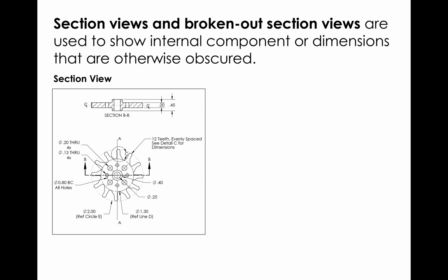Okay, so this is the trigger. This is my drawing, or I'm sorry, of the chamber. This is my drawing of the chamber. Okay, and you'll see that we have a section view here. Section BB is as if we cut through the chamber right along this axis marked BB, and then we get to see it in cross section. Okay, so this would be a section view on a part that gives us the shape, right? This is very easy to now see the shape and exactly where these interior holes are placed. Okay, so that makes for a nice section view there on the part level.